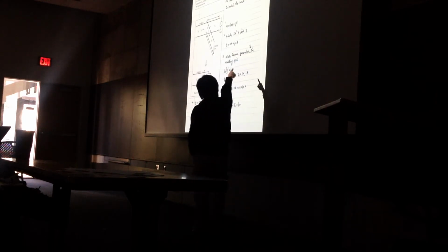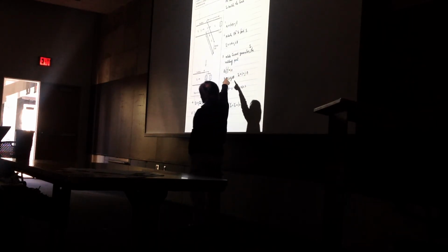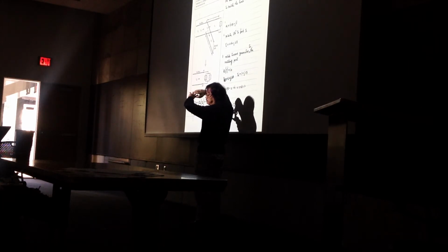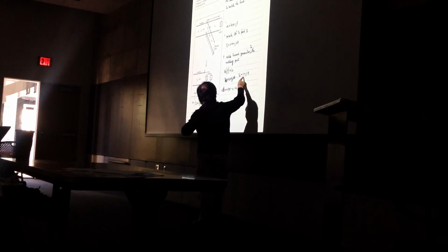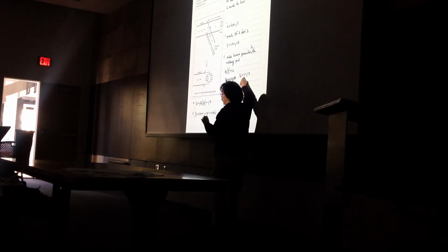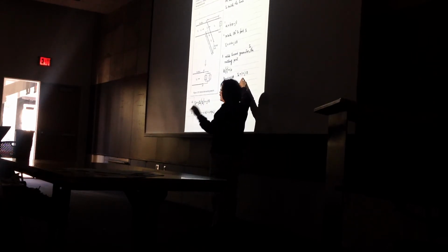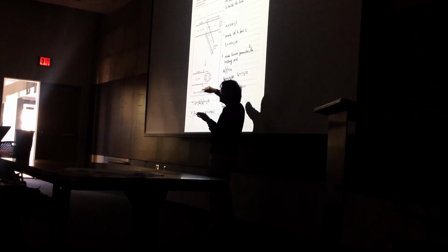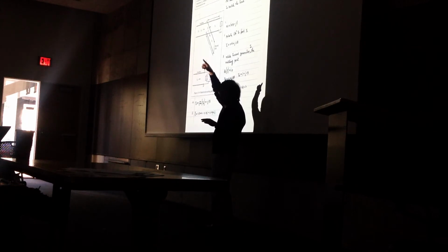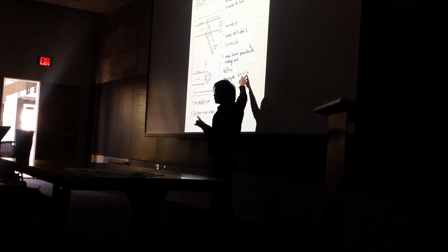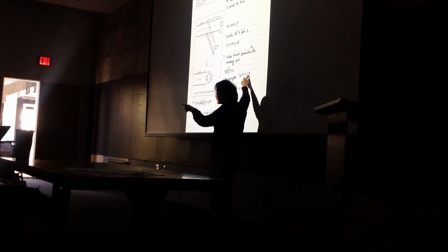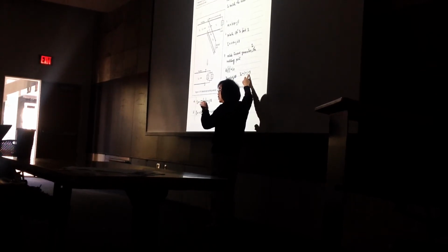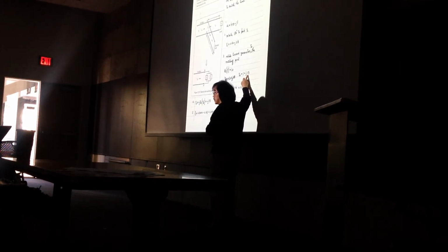And rotate it toward the generator to the matching point where the real part is equal to 1. That's where we say the intersect of these two circles. And that tells you at that location your real part must be equal to 1. What is your imaginary part? You look at that point intersect with the XL location, and this time it is 1.5. So that means you need to provide a matching of a minus j1.5 to cancel it out.